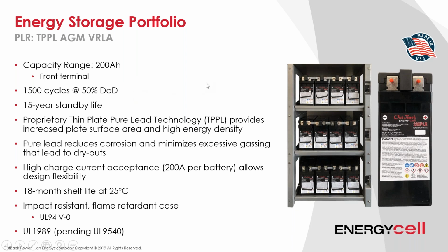The temperature rating is extended, it has an 18-month shelf life, so the self-discharge is really low on a pure lead battery, super low. So there's very little parasitic load on it. It's just really pretty good technology. And these can have like a 15-year standby life. Only thing about the pure lead, it only has 1,500 cycles at 50% depth of discharge, which, compared to older AGM technology, is actually pretty competitive. But do keep this in mind.